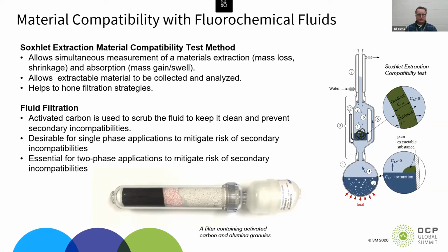And that points to my last point related to fluid filtration. When we sell a fluorochemical fluid, it's very pure. And in order to be able to ensure that it's going to behave the way we intend, we like to keep it pure. And so we will typically clean the fluid in situ. Activated carbon is a very good way to do this. It'll effectively scrub contaminants, plasticizers, things like that.